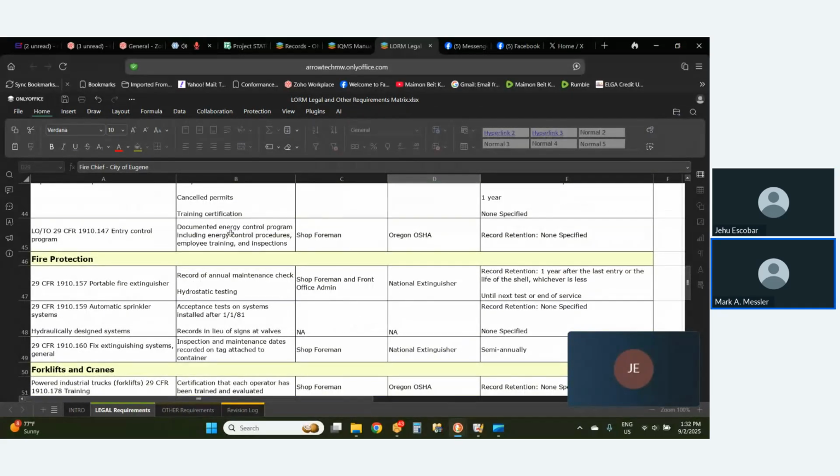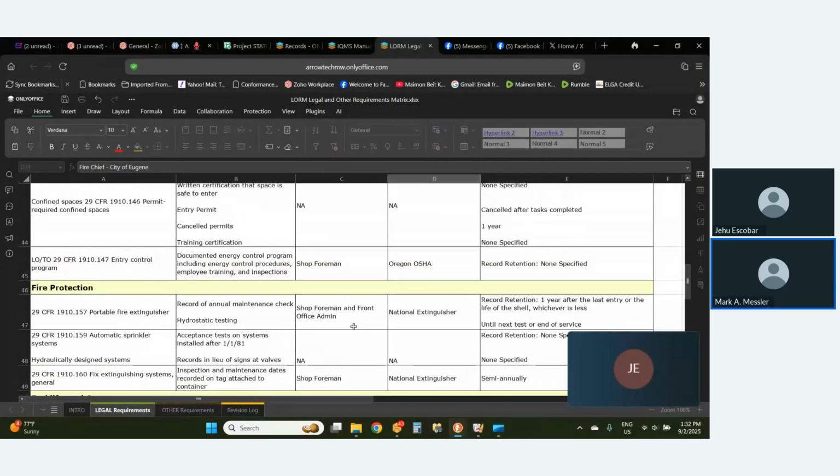Yeah, confined entry is basically... We see it a lot in steel stamping, where they have what they call press pits, where the steel comes off of the coil and then goes down into a pit that keeps the feeder from putting pressure on the decoiler. And those things are really hazardous as all get out.